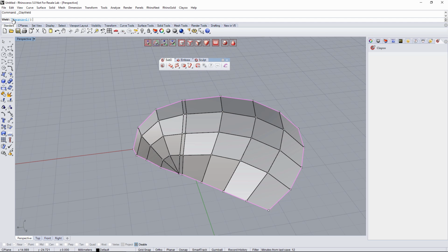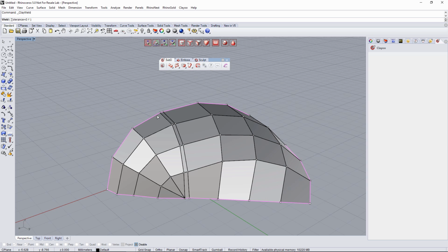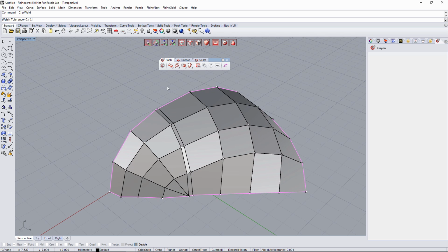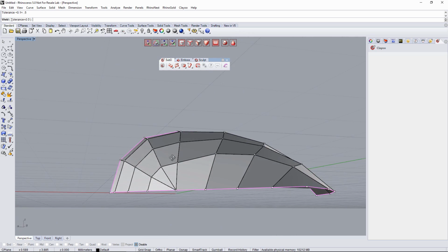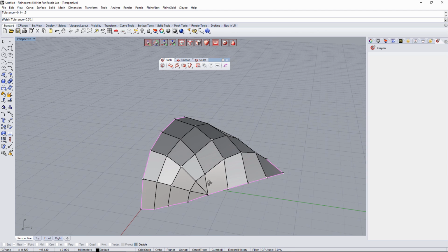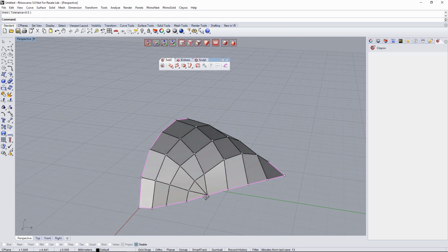So by default, it's going to set the tolerance to 0.1. As the points were so close, we just get this tolerance, so we can get this job perfectly done. If we increase the tolerance in here, imagine that we want to join this point in here, we can increase it, instead of 0.1, I think 0.5, for instance, and now we have joined all these points. Maybe it's also a good way to do that. Okay, so let's go like this. And I'm gonna right click to validate.